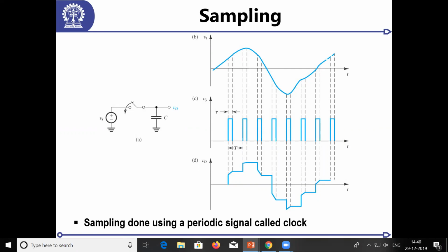Now this is an RC circuit, right? A simple RC circuit with a switch, a resistance, and this capacitor. When you're designing this sampling circuit, there are a few things that govern how you should size this capacitor and this resistor, and that will decide the quality of your data converter, because this is finally the input which is going to be digitized by your ADC.